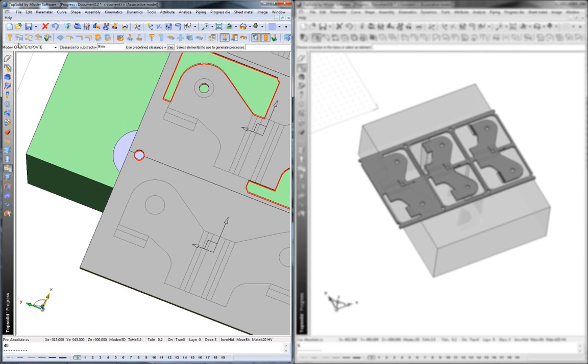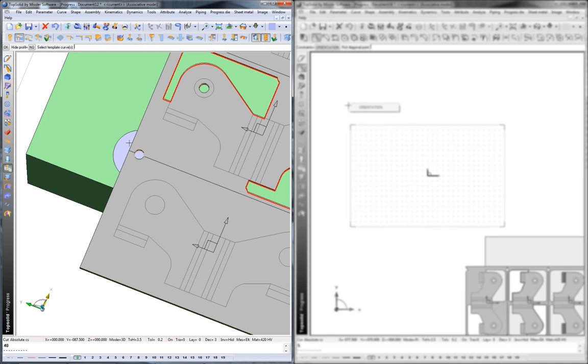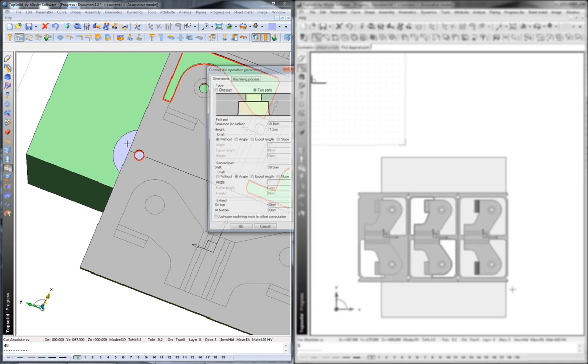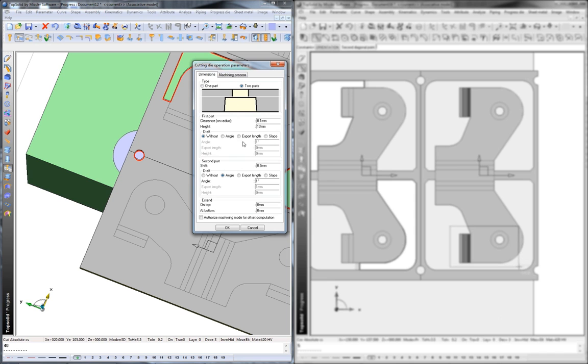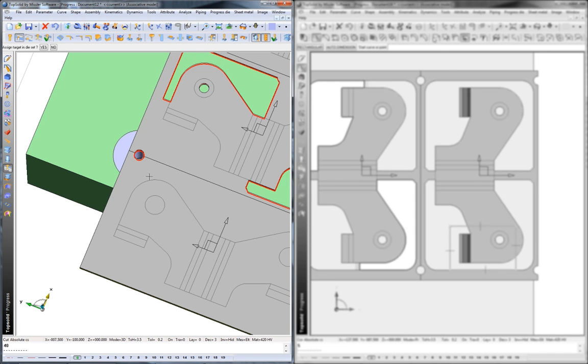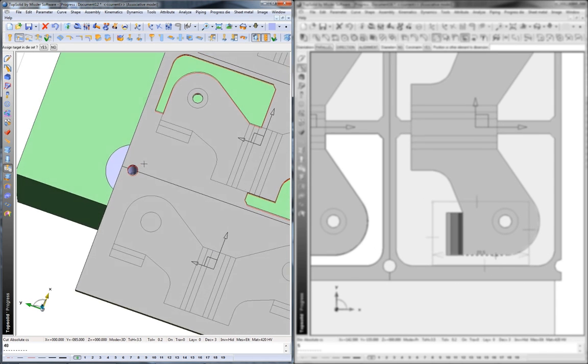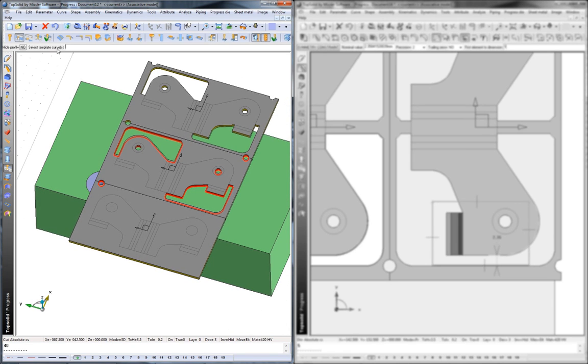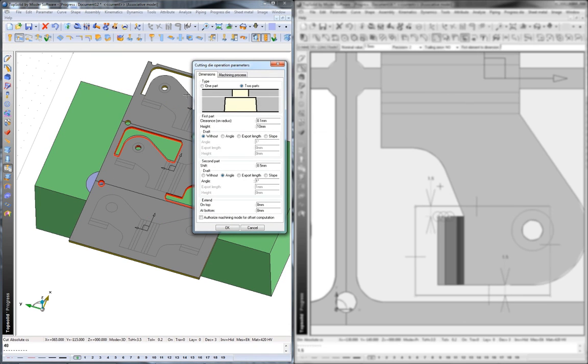What else can we do? Ah, yes, let's make our actual relief through there. So we'll select that, we'll select the plate we want to modify or this new insert that he made. And we'll choose how we want to relieve that. Like that, TopSolid does the work for us. Let's keep going. Let's maybe make this cut out. In this case, maybe what we want to do is give it an angular relief.